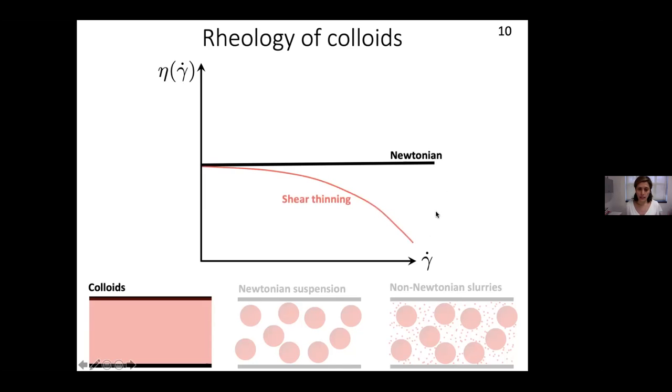That's a Newtonian material. So when we have shear thinning material, it means that as we shear the material, the viscosity drops, or the rheology can be shear thickening, meaning that the interaction of colloidal forces, contact, and other forces in the system would give me a rheology where the viscosity increases as a function of shear rate.